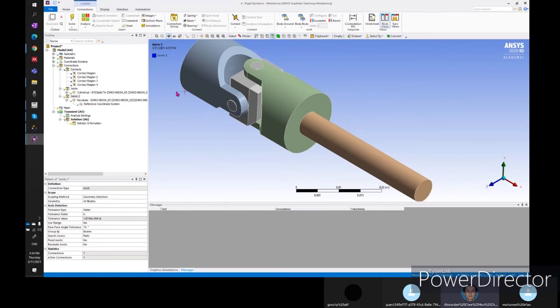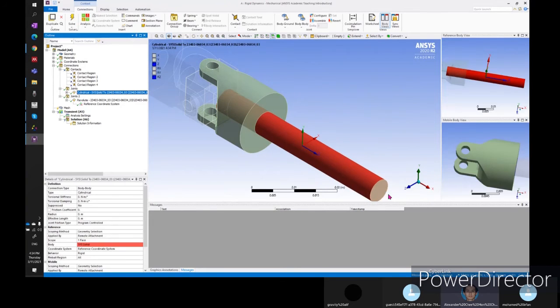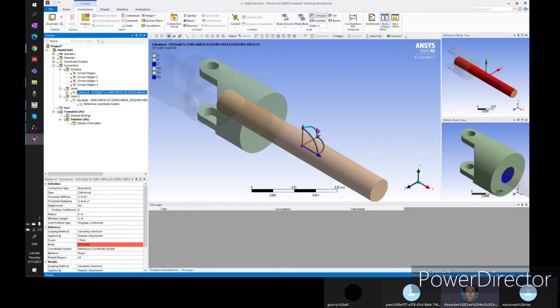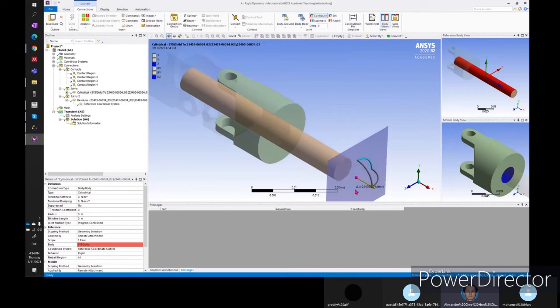And they are linking. Just now, for the cylindrical, when I was trying to pull or rotate, the holder was not following me because the holder did not have any relation with the other parts. But now they already have a relation with this pin. So if I configure my cylindrical, especially on the rotation, you will find that, look at behind the part, they're following. Just now it doesn't follow, right? And then after that, when we move, you can see that they're also following.